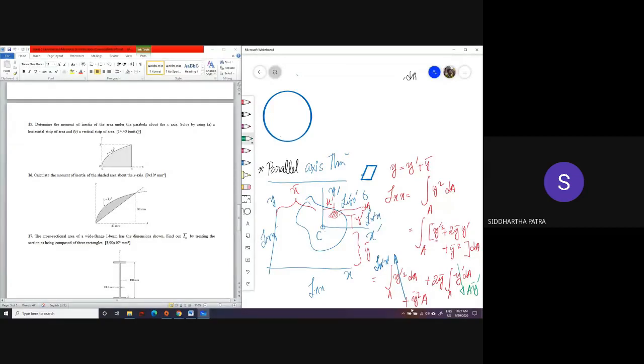It is the y coordinate of the centroid measured with respect to the centroid. Centroid is in the middle. Some y would be positive and some y would be negative. When you take the weighted average of that, you get the coordinate of the centroid with respect to itself, which means this quantity is 0.